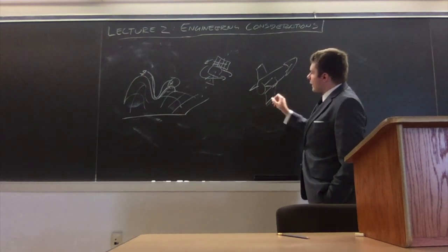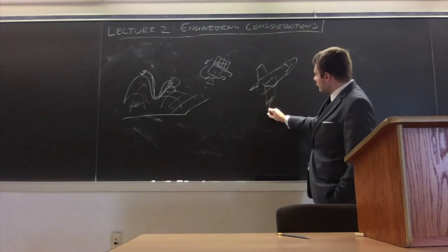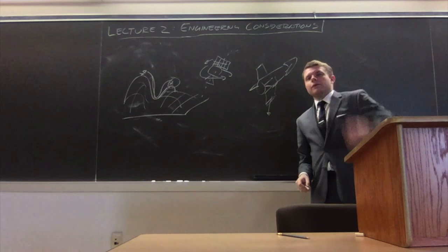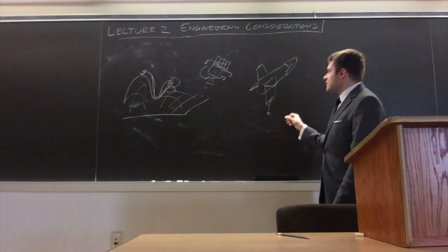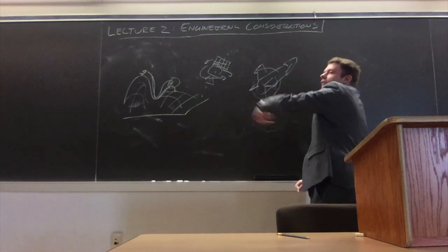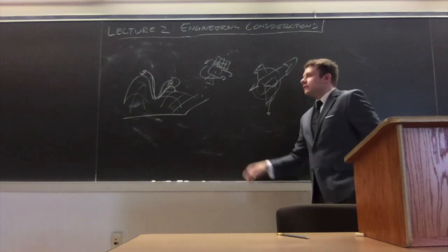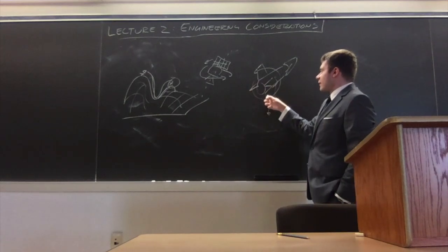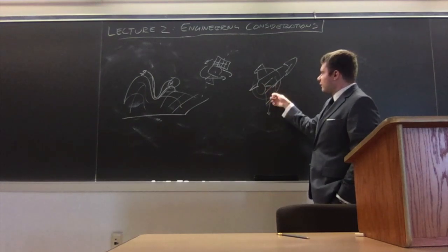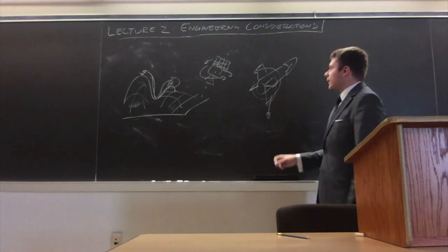Because if your fin's off by like 1/10 of a degree, really, really hard to see, but still there, you have a little vector coming off of it that's a little skewed. And that means your rocket's going to start wanting to go off and do its own thing in that general direction. So by spinning it, you take that error and you average it out over a much larger area, and it kind of partially self-cancels. So you can constrain your error to much greater errors from build and design or what have you. You can constrain that more effectively if you have the ability to just kind of say, we're just going to average out across the whole thing and call it a day.